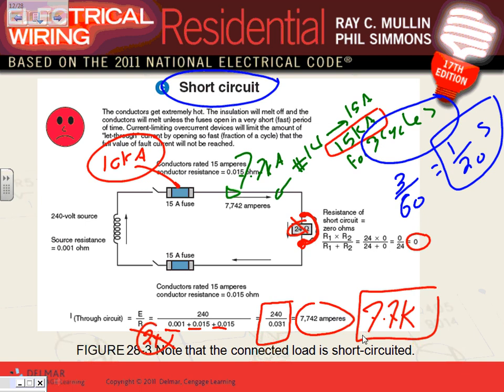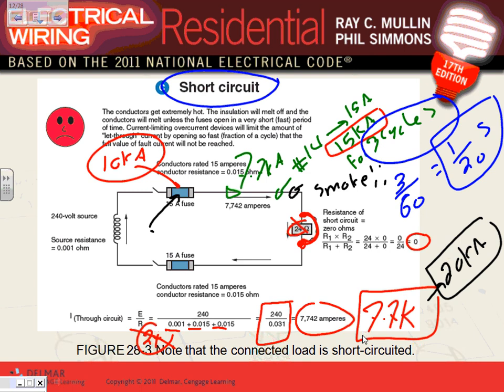Now, Oladipo, let me give you this scenario. Suppose that this current was, let's say, 20,000 amps. Number one, what's going to happen to your circuit conductor here? Smoke. There's still smoke, right? What's going to happen to this guy? Explode, or weld, not open. If the available short circuit is this amount, it's not rated to handle that.